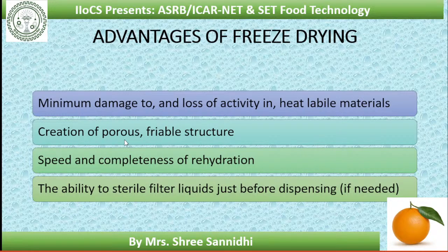Creation of a porous and friable structure gives a better quality of freeze dried product. So the rehydration capacity is also more. Speed and completeness of rehydration is more. The ability to sterile filter liquids just before dispensing is easy.